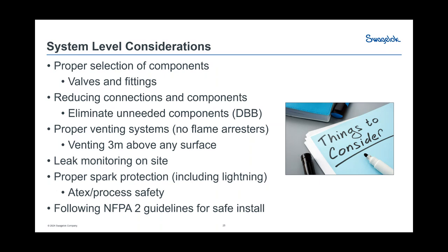The really, really important thing about hydrogen systems is, by standard and by the CSA standards for infrastructure and vehicles, you have to consider every joint to have a 10 standard cc's per hour leak rate. Well, what does that mean? That means when you do calculations for safety, if this is in an enclosure, you add them all up, you figure out how much 10 cc's per hour would be and how much that would be volumetrically inside of your enclosure, and you're not able to go over a 1% threshold of hydrogen in air for safety reasons.